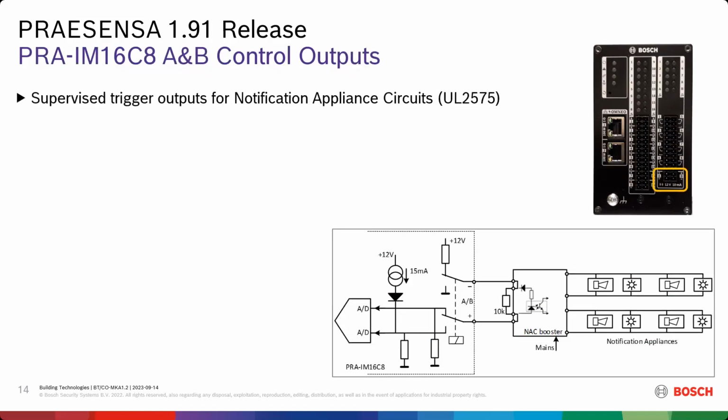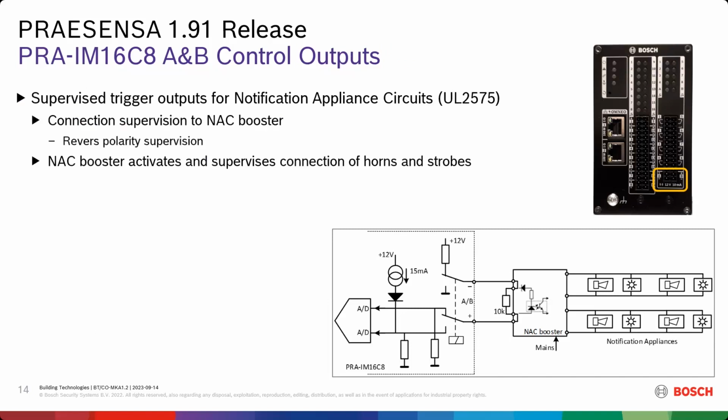These are supervised trigger outputs, and they are especially interesting for the UL market because you can now also supervise these NAC devices, like these NAC boosters for indicators, for example. So this connection supervision reverses the polarity to be able to be sure that the connection is still there, and in a normal operation mode, it then activates the horns or the strobes which are connected to that booster.